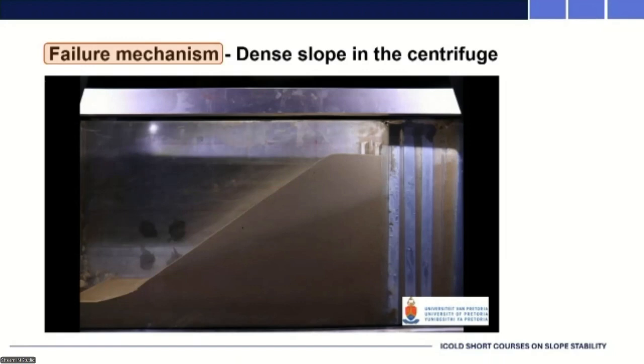So this is in our geotechnical centrifuge where we prepared a soil slope at a dense state, and we allowed the water table to rise, and we wanted to observe how it failed. You can see that the water table is rising, and then when it touches the toe, we start to get sloughing at the toe, propagating backwards, and the soil comes to lie at an angle that you can calculate for flow parallel to a sloping surface, but never do we get a very dramatic failure.